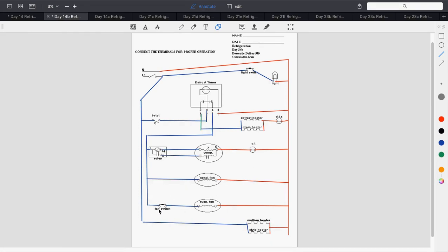And you'll also see this a lot in the deep freezers that people have in their houses. The single door deep freeze, either the chest type freezer or the upright type freezer. You see this a lot. We shut off the evaporator fan when the door is open. It prevents ice buildup.